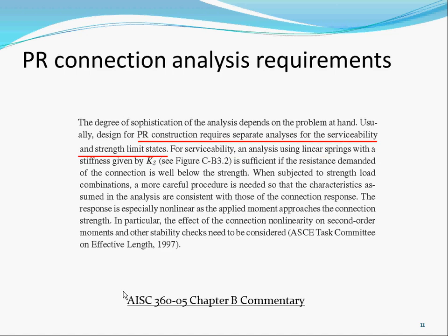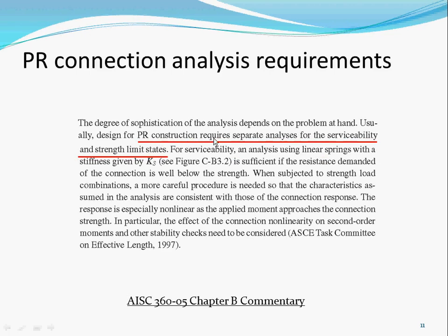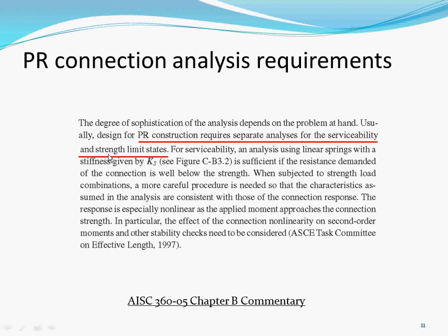Some more commentary: PR connections require a separate analysis for serviceability and strength limit states. What they mean here is serviceability is typically for your drift check, for your deflection check.